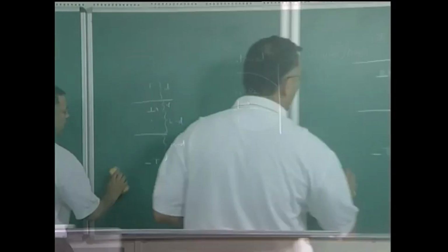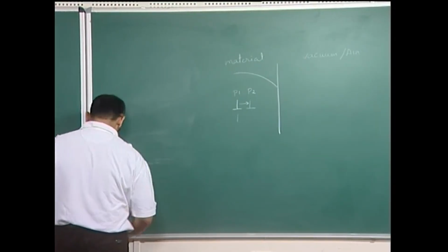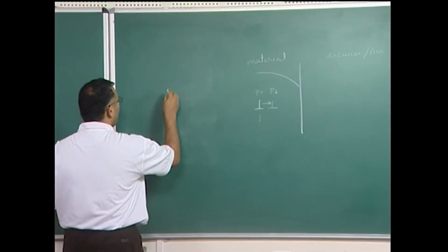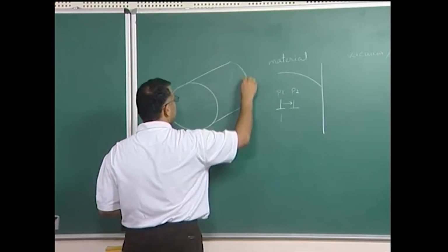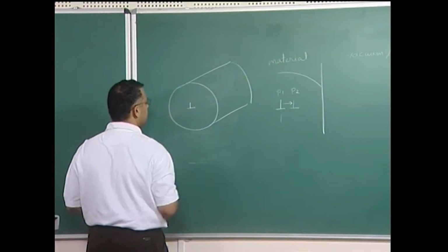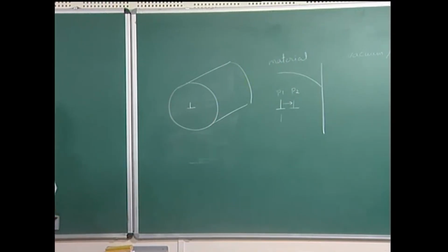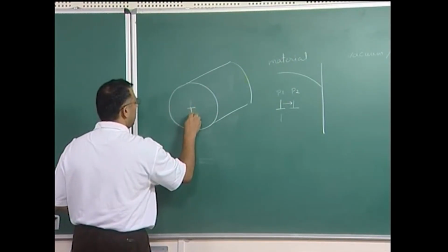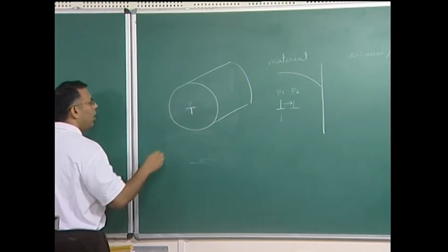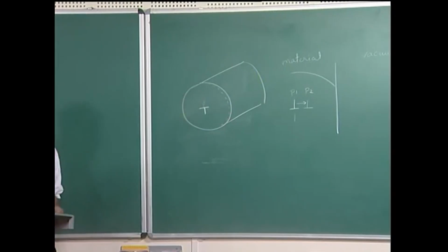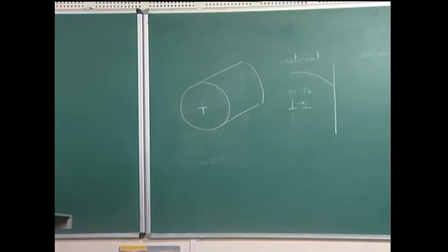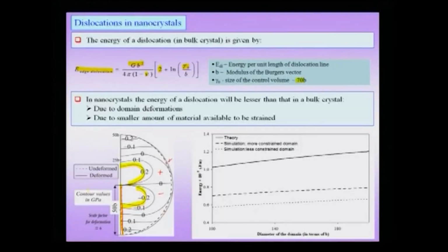Now, of course, to draw this whole body, this is actually not cylindrical in 3 dimensions. So, let me draw the full geometry for you here on the board. You have a cylinder going in the 3rd dimension like this, and my dislocation is located here. To be consistent with the geometry there, I will actually draw the extra half plane below. So, this is my dislocation, and now my body is getting distorted in the presence of this dislocation in a cylindrical body.